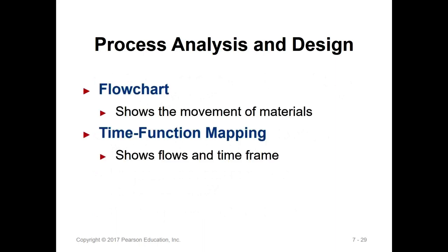So, in the process chart, when you design a process, when you analyze the process, normally we like to use certain tools. The tools that we implement over here are the flow chart and the time function mapping. Flow chart is very simple. It just shows the movement of the materials, and the time function chart is going to not only show the material flows, but also give you an idea about the time. Each step, how much time it is going to take to finish.